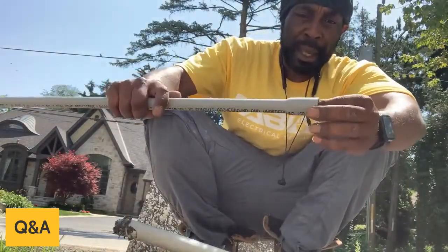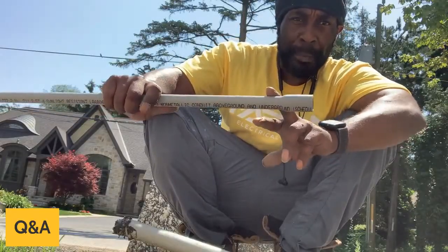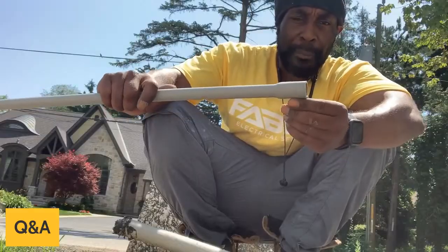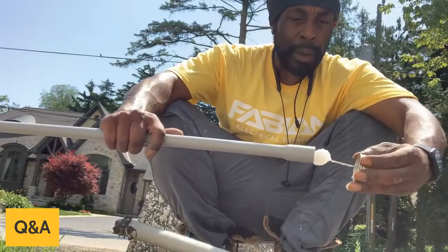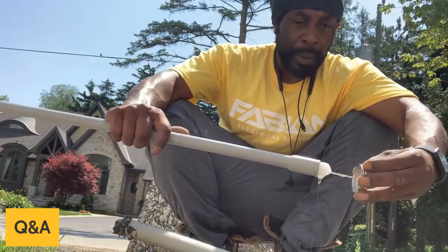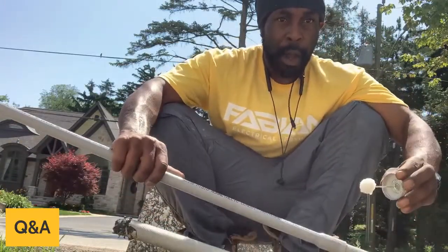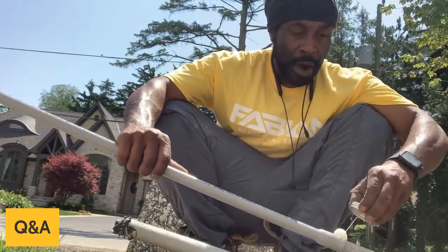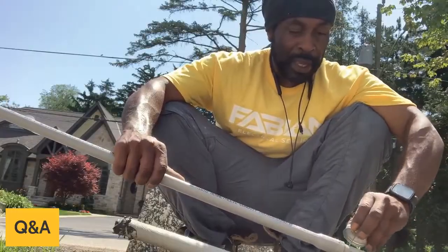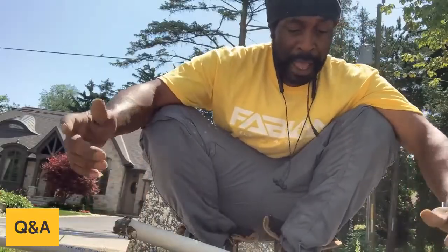This acts like a coupling, same thing. This is how they come, ten-foot lengths. Some guys call it a bell end, but this is what you call a half-inch coupling also. Normally what I do at the end, I'll place my glue around here. That way it's firm, secure. Twist at the end to make sure it's not moving. That piece is done. And then we're going to move on to the other piece.